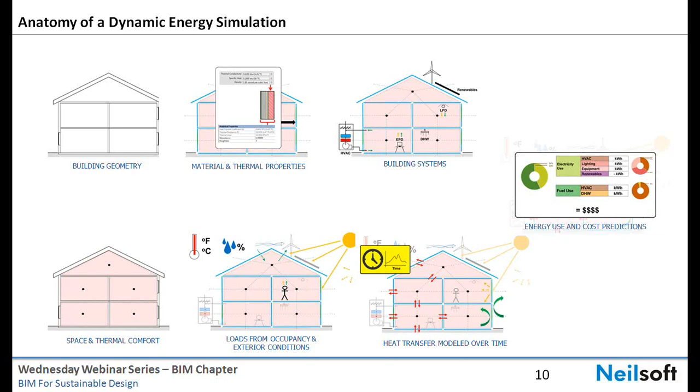In a conventional energy analysis process, there was a method in which we used to link an AutoCAD drawing and create a building geometry specifically for performing the energy analysis. But here, when we are using a BIM model, the same model which is used for the conceptual stage for visualization can be used for energy analysis. Those geometries which are made for the conceptual stage visualization can also be used for the energy analysis, and it cuts down the time for energy analysis very rapidly.